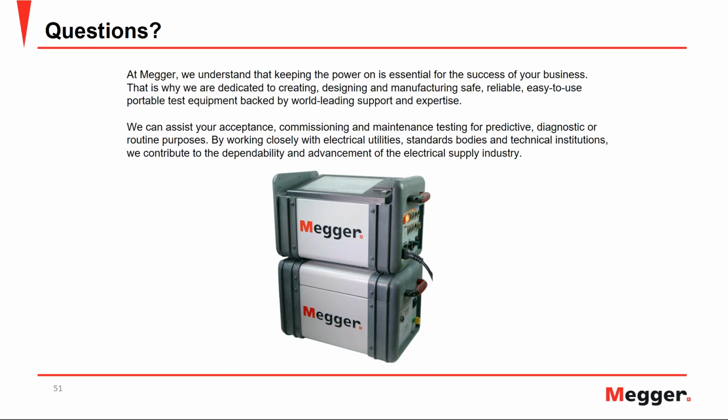When we talk about liquid filled transformers, your power factor value should not be voltage dependent. In other words, if you perform the test at 2.5 kV, 5 kV, 10 kV, you should expect the same results. And because of that reason, there is no value in performing a tip-up test unless you have PD activity going on inside the transformer. So that's for liquid filled transformers.